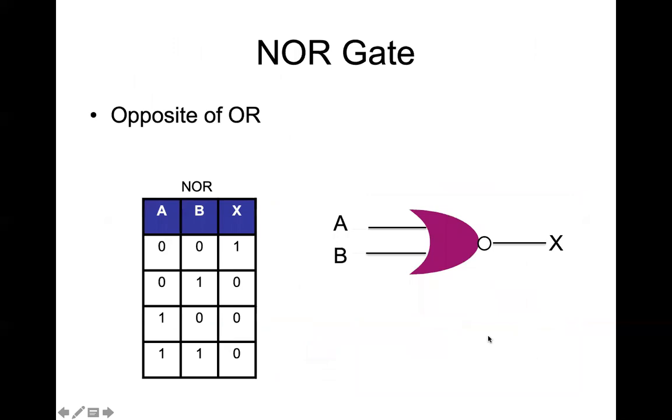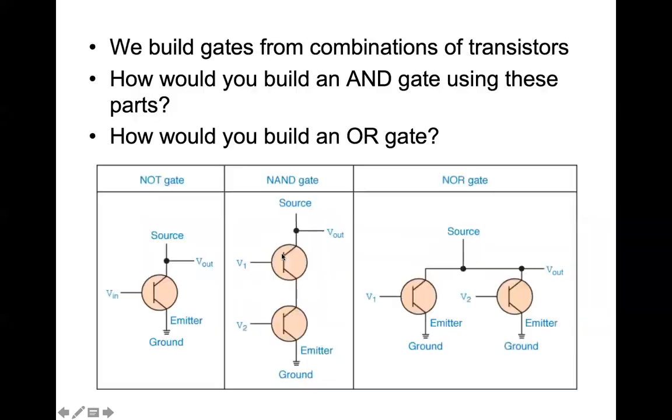So if we cycle back to the slide, you can see that if either input wire is high or both of them, one of the switches gets closed or both, and we pull the output low. And in the last case that we already talked about, the output stays low. So what this shows is that NAND gates and NOR gates are, in some sense, more fundamental. They're easier to build than AND and OR gates, but they're a little bit harder to talk about using logic. And so we consider those the more derivative gates. But in practice, these may be the more fundamental and easy to build things.